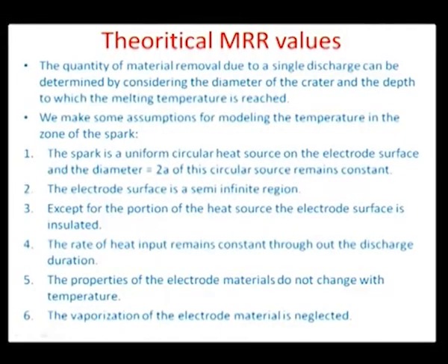So theoretically, if we were to estimate the material removal rate values, we really need to consider the heat transfer process between one such spark which is happening over a certain surface and the way it delivers the heat energy to cause the material to melt and go out. So let us now see how to estimate the quantity of the material removal due to such a single discharge or single spark, and this can be determined by considering the diameter of the crater and the depth to which the